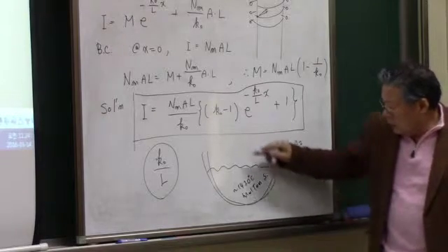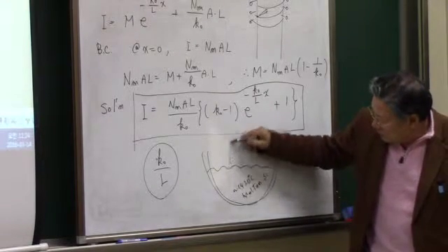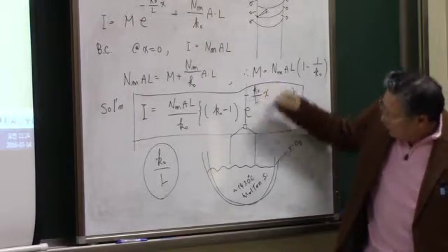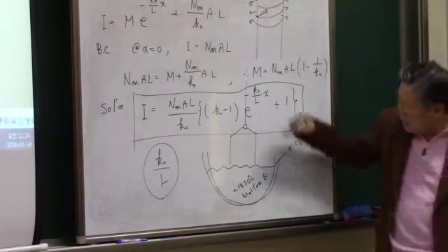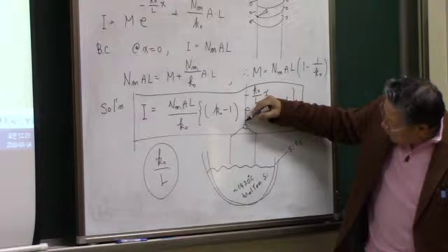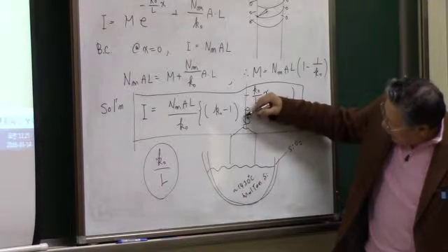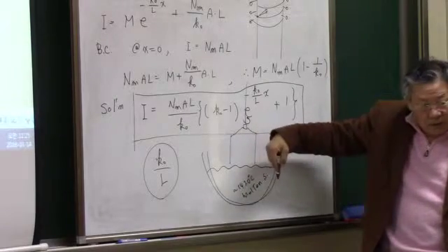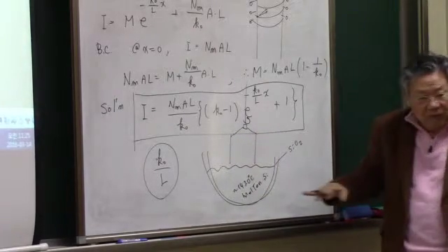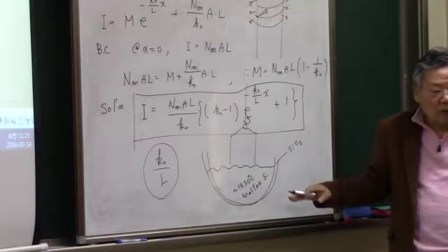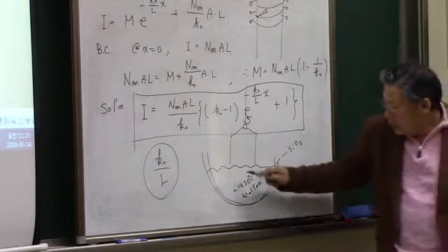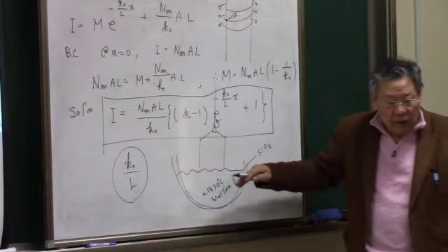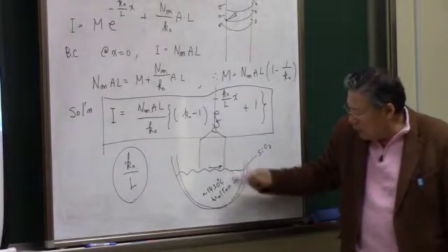And then in crystal growing, we have a tiny single crystal silicon seed, and that is rotating along this horizontal axis to make a uniform distribution of the temperature, dopants, whatsoever. Okay, it has a uniform crystal growing along the radial directions.